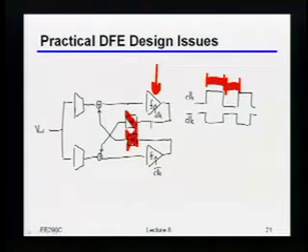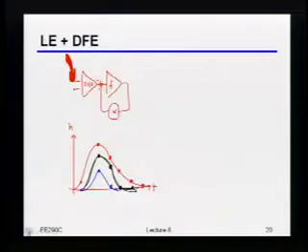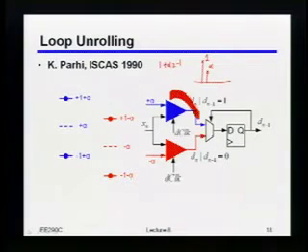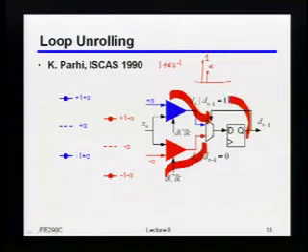Well, so imagine that I wasn't doing any DFE at all, right? If I wasn't doing any DFE at all, that's clear, right? If I'm now doing DFE, then you're right, to actually see it, you have to really walk through the timing path for the loop unroll. But basically, it turns out that the delay of the comparator, as long as this forward path is not the critical one, you're somewhat insensitive to it because basically you're going to be getting a delay from the comparator on the other way. So as long as they arrive at roughly the same time, then as long as this forward path isn't the critical one, they don't really eat into this feedback path. That's kind of what it comes down to. Again, that's under the assumption that the feedback path is the critical one, not the forward one, which may or may not be the case.